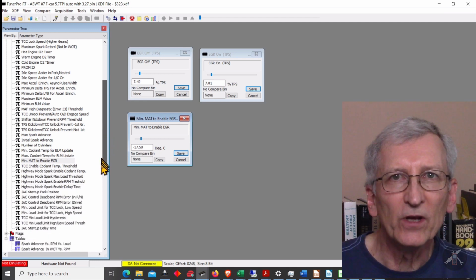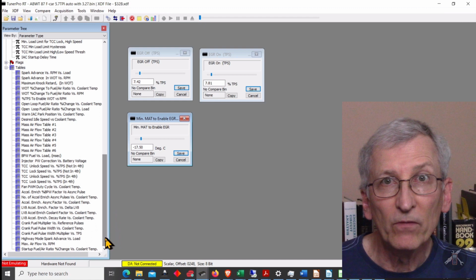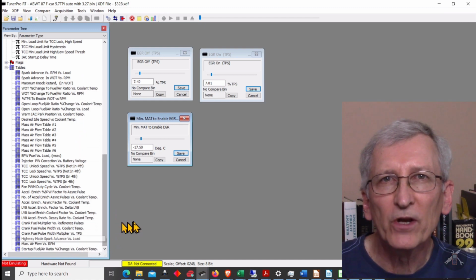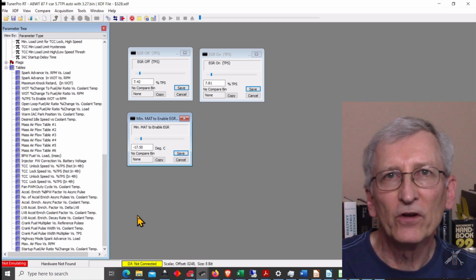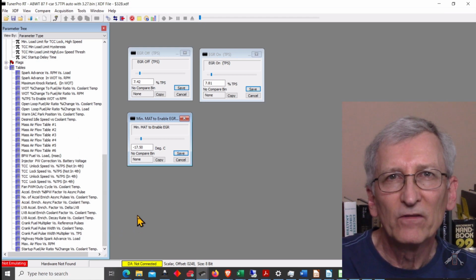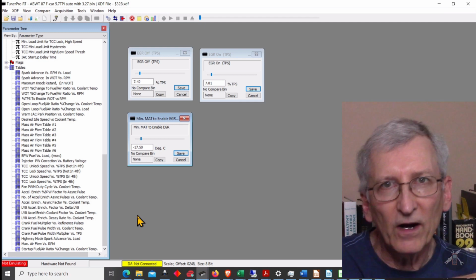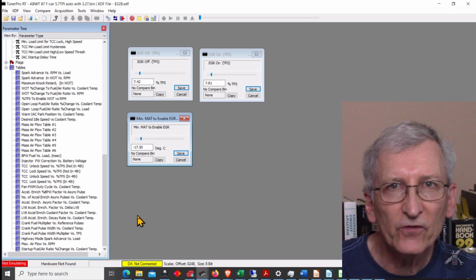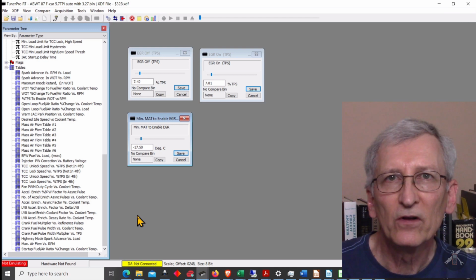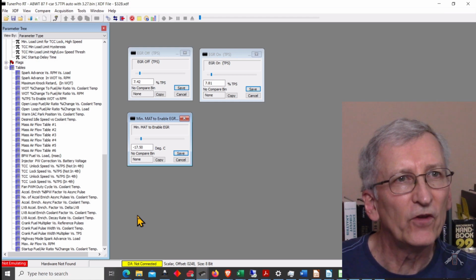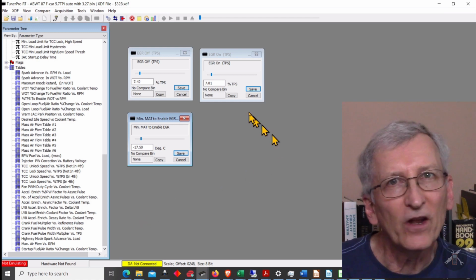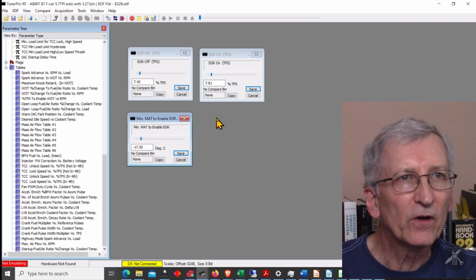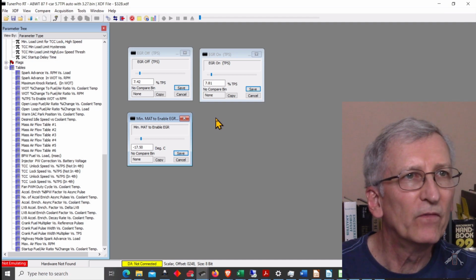this would suggest to me that they took the table and calibrated it out, and it goes back to what we just showed a minute ago with the '86 Corvette, where it was either 0 or everything. I think this is either 0 or everything. I think this confirms what Mike is seeing. I think it's correct. He's getting either no EGR at all, if he's below 7.81, or he's getting everything. So I'm going to hold that one. I'm going to set that to the side here a little bit.